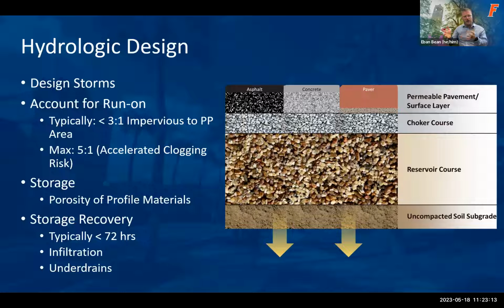If you have a very high impervious to permeable pavement area ratio, in some really intense events you may have a high enough runoff rate to get up to the limit of the surface infiltration rate, but that would only be in very limited situations, when there's probably some maintenance that needs to be done on the surface anyway.